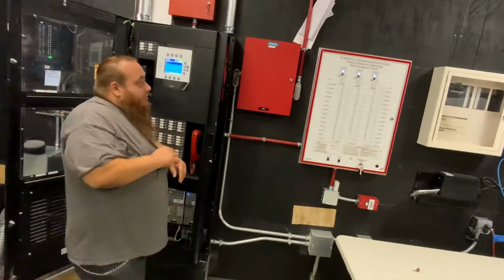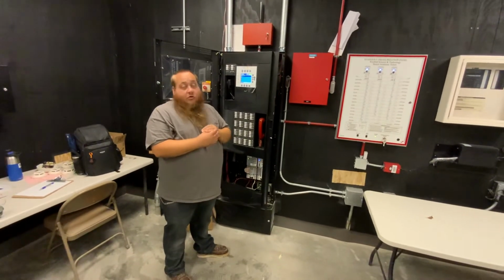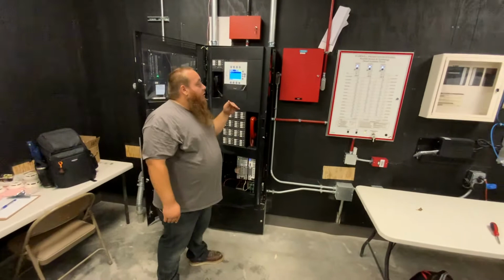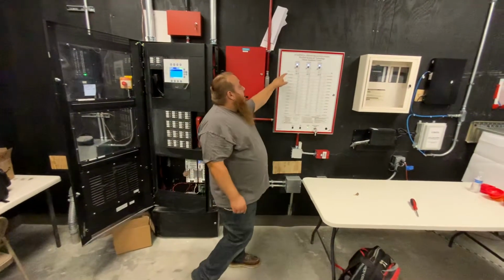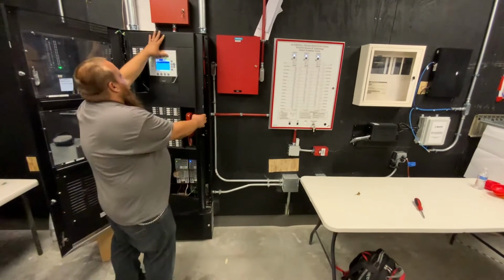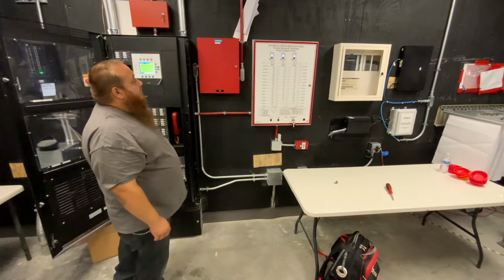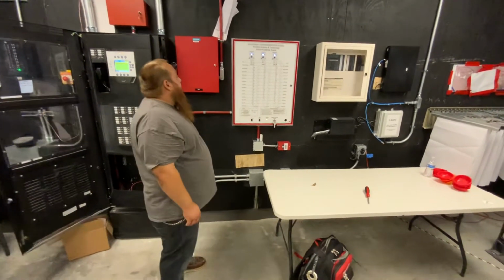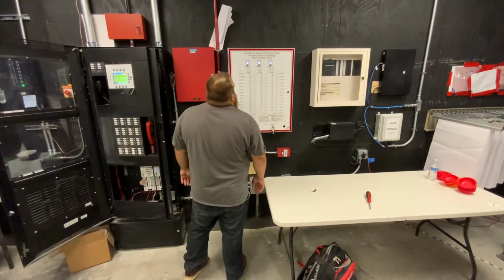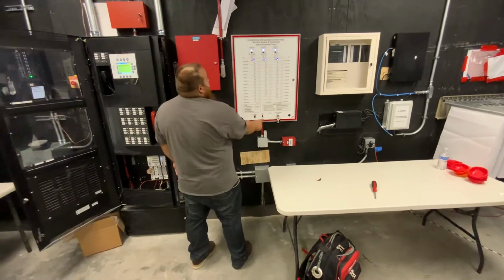And with these stairwells, each stairwell has an airflow pressure sensor. So once those sensors come up to certain air pressure, then that will confirm that your fan will be coming on soon. Unless everyone has the doors open, it takes a while. You can do a lamp test just in case.